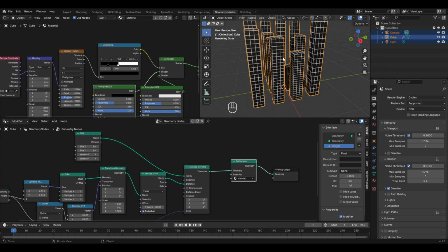And it might be possible that some of you might be having some doubts here, so let's revise each and everything that we have done in the shader editor till now. See, to get these windows, we first added this Wave texture, made some changes here and ended up getting some square spots which slightly look like windows. Then we added this color ramp and we used the pointers here to change the position, or basically the thickness of the borders of these windows.